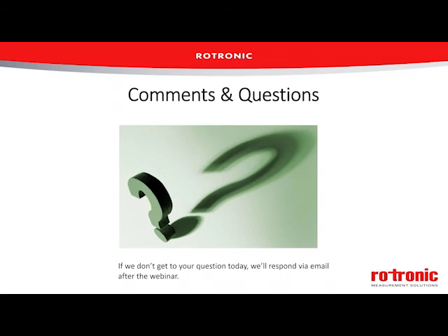How about you, Bruce? Well, when I think of superheated steam, I think of my old Navy days when I was an engineer officer on an old steamship, and it was 1,200 psi steam running that plant. I can tell you, there's no way you're going to measure that steam. So it depends on pressure and it depends on temperature. Any steam measurement, especially if you're using a capacitive sensor, is very, very difficult. They don't like that environment at all.